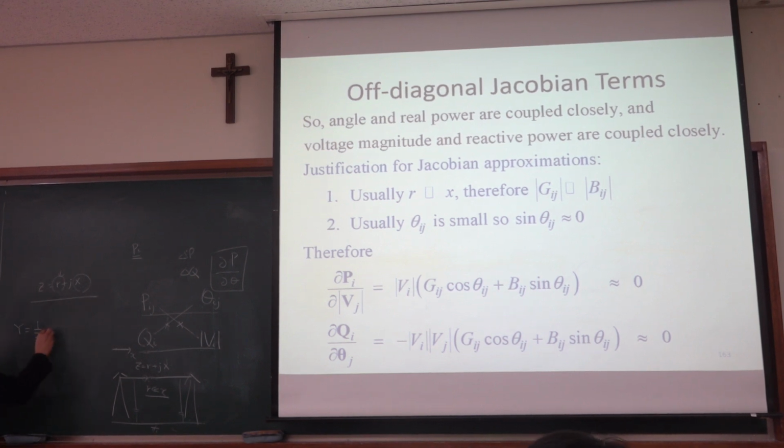Really? So this is right? And this is (R minus jX) over (R squared plus X squared), right? And then this is the real part, conductance, and then this is susceptance, right? And if we have this relationship, anyway, this is very small. Okay, even though R is very small, we have very little resistance, the conductance is also small because X is dominant. But when you focus on this imaginary part, this is negligible. So the imaginary part, the susceptance is 1 over X.